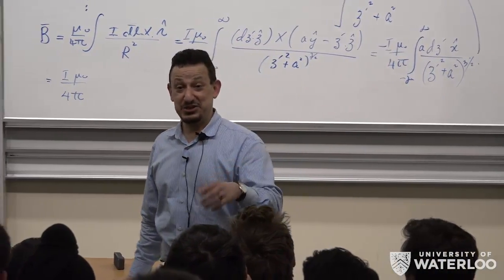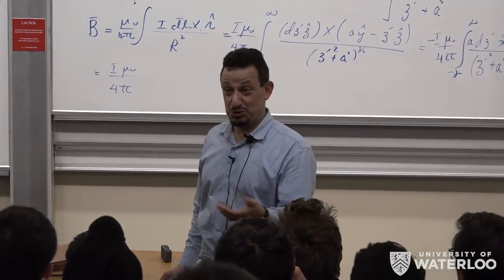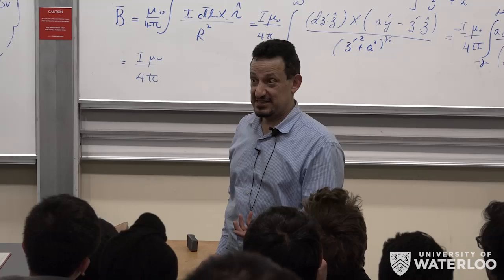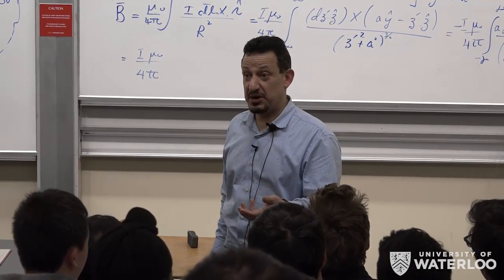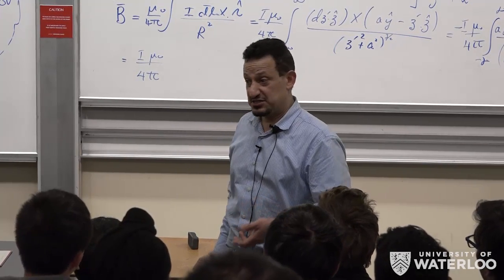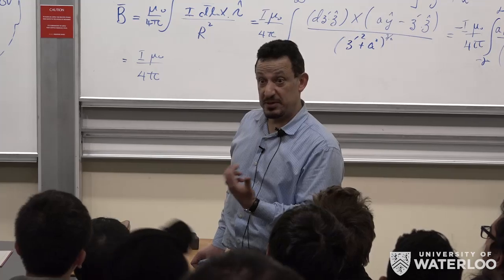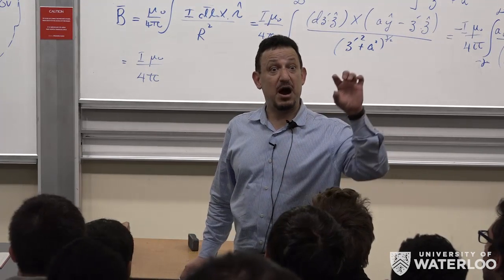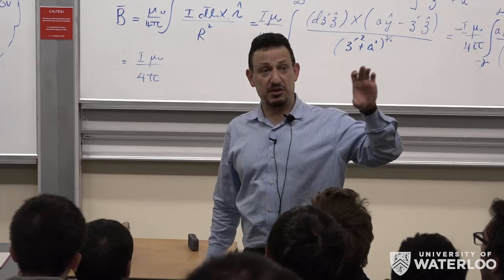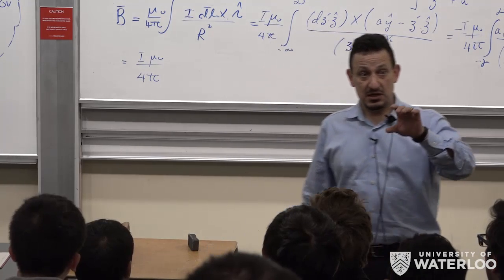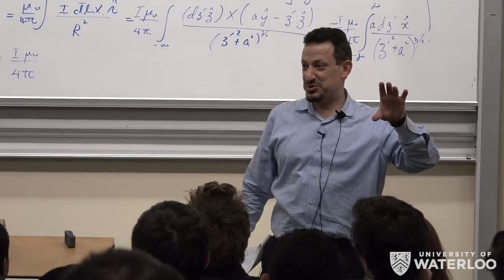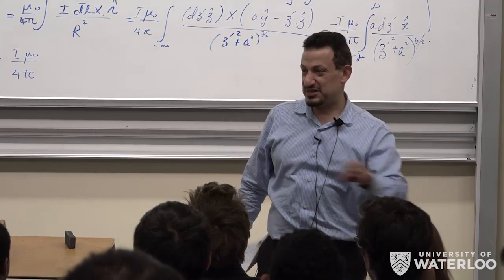So practically you're shorting it, and that's why you get this huge spike. When you get this spike, you're drawing a lot of current from the battery, which means the power being kicked out of the battery with time is increasing, and then it says, oh, I can't deliver any more power. So this model breaks down.